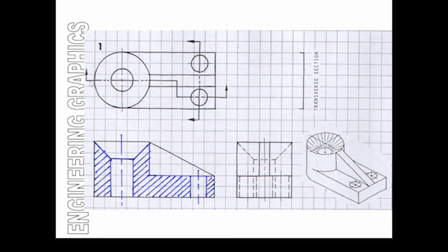Finally, we have a staggered sectional view here to contain all the details of this cylinder, and also the designer decided to step down and take that on in the same view. And as you can probably say, the front view is basically a representation of this, judging by the cutting plane and direction. And there would be a side view here, which I don't think is shown in this particular view, but the side view will be whatever you see from that side after you remove items on the right hand side of the cutting plane.